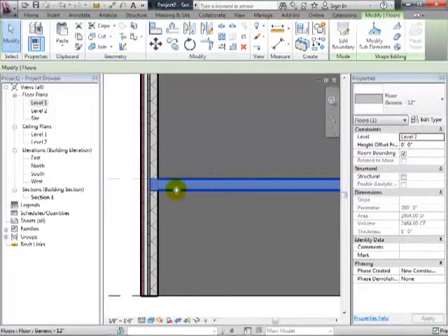Now, go ahead and just move one of those pink lines ever so slightly. Go ahead and use the ones that aren't really intersecting. Just need to make some change to the boundary. And then when you click the green finish check mark, it should ask you the question again. So say yes this time. Now go back to your section view, and it will do the intersection the way you want.